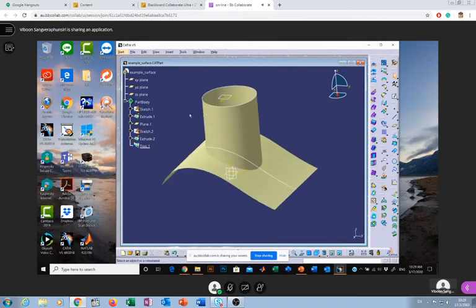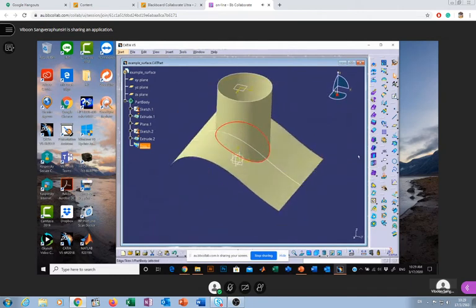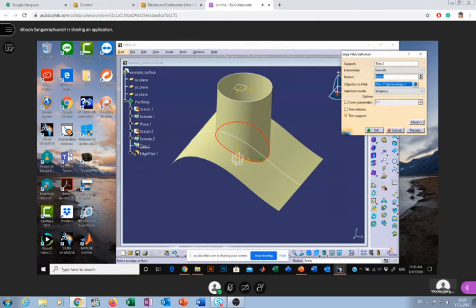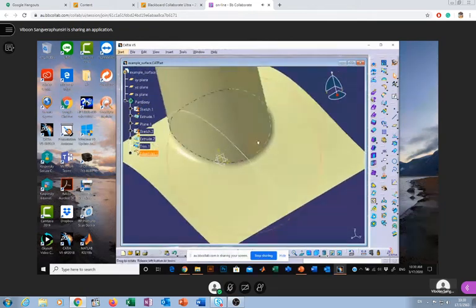You can do a fillet here. You want to assign a fillet here. You can use this fillet command. We have shape fillet and fillet; this one has to be a fillet. Select this one. How much? Let's say you can use 5, or you can increase it, let's say 7. Preview this one, and you have this.